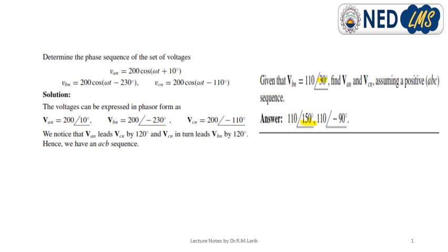And the third voltage, that is VCN, is behind the first voltage by 240, and you may subtract 120, that is the second voltage. It is behind the third one by 120. So if from 30 degrees you subtract 120 degrees, you get minus 90 degrees. So you will get the positive sequence voltages. All positive sequence voltages are there. Very simple.